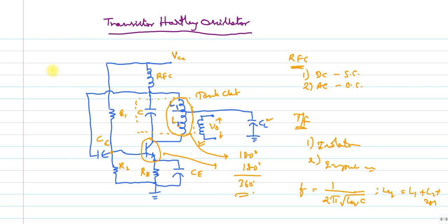Then what is the condition for sustained oscillations? The condition is that hFE is greater than or equal to (L1 plus M) divided by (L2 plus M).